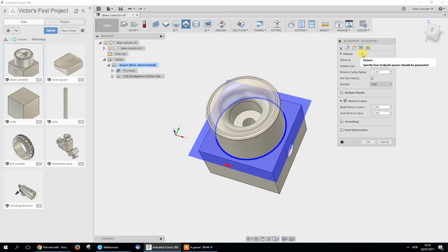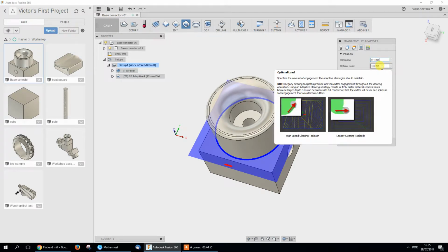So what we do is, instead of going the whole tool diameter and removing the material, we're just going to define 1 millimeter or even half a millimeter on the side of the tool to remove, and make a lot of passes, removing material each time along the whole height. Instead of the same millimeter doing this again and again across the whole diameter of the tool, which wears too fast. We'll see this a little better on the simulation. So again, tolerance, we can leave it at 0.1 because we're going to make a finishing pass after.